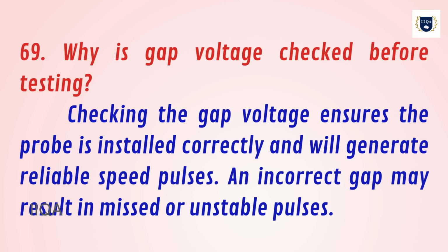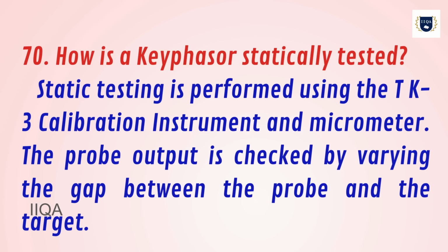69. Why is gap voltage checked before testing? Checking the gap voltage ensures the probe is installed correctly and will generate reliable speed pulses. An incorrect gap may result in missed or unstable pulses.